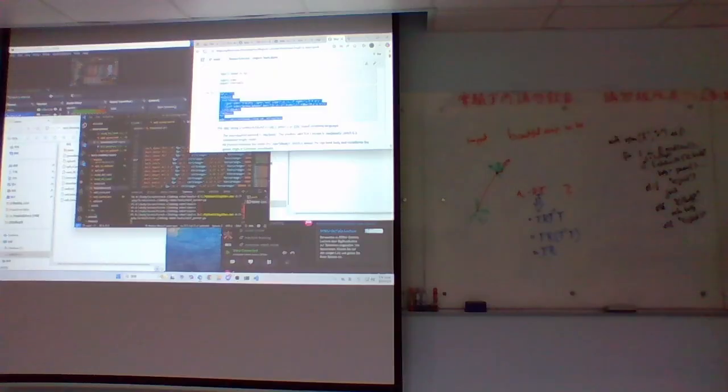We always have three points that are holding onto the wall, like in this case, these three. The center of mass of the robot has to be within this triangle, and then this joint is free to move. And that's the only kind of climbing we're doing. We're not doing dynamic or toppling or anything like that.